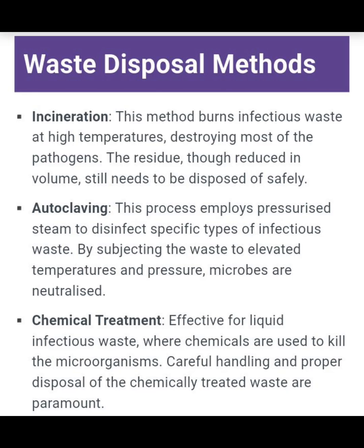By subjecting the waste to elevated temperatures and pressures, microbes are neutralized. 3. Chemical treatment. Effective for liquid infectious waste, where chemicals are used to kill the microorganisms. Careful handling and proper disposal of the chemically treated waste are paramount. During incineration, it is proper to know that incinerators should not be kept around where people stay.